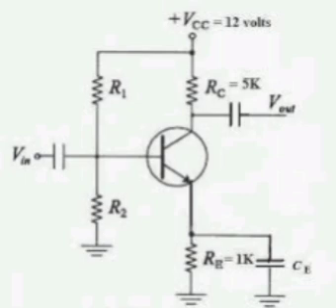Here, for the N channel MOSFET, the arrow is towards the drain. Input is given to Vin and Vg is the gate voltage. The transistor is defined as M1, and from its source we take Vout, in series with RL, then Vout is taken as the output across RL. So if Vin is very small, VDS is very small, hence the MOSFET is in the linear region, and it acts as a resistor.